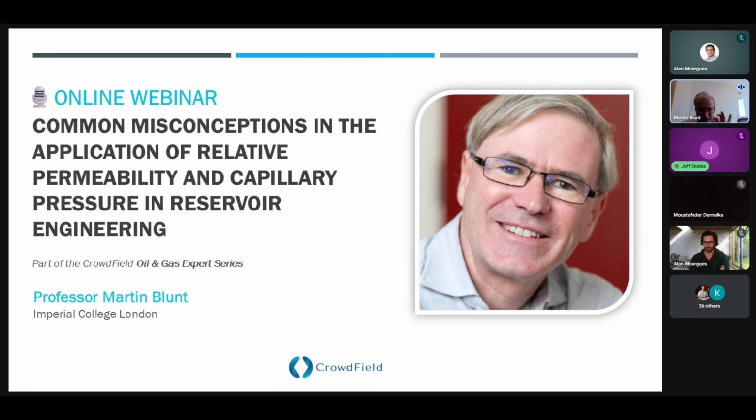The correct behavior will be to incorporate now a water flood capillary pressure, like I showed in one of my previous slides, combined with the relevant relative permeabilities. What most simulators do, because that's quite complex, because now you've ended up with two sets of capillary pressure, is they just ignore the capillary pressure term in the macroscopic flow equations. So it is an assumption. If you're looking at really field scale behavior, it's probably not the worst assumption in the world, to be honest. But yes, you're right, it is an assumption.